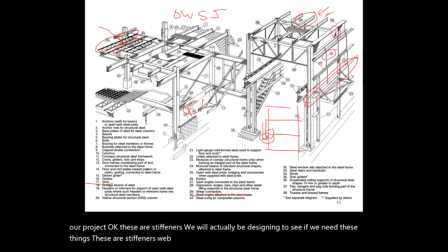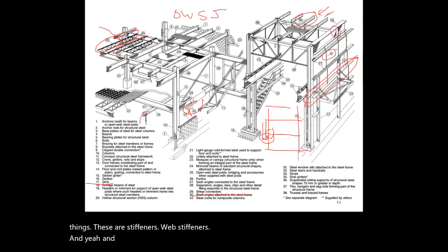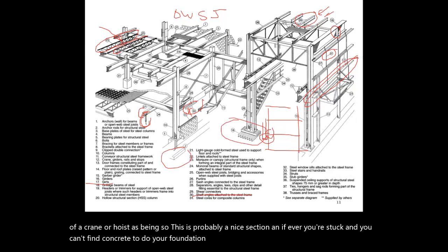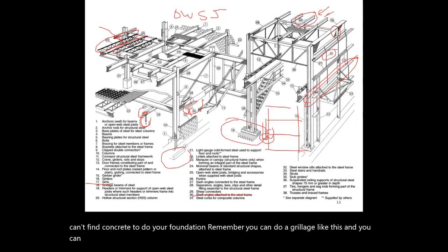And oh yeah, this is probably an I section, because you see there's a bit of a crane or a hoist. And if ever you're stuck and you can't find concrete to do your foundations, remember you can do a grillage like this, and you can make a foundation out of steel if you need to. As long as you help distribute the load, it works.